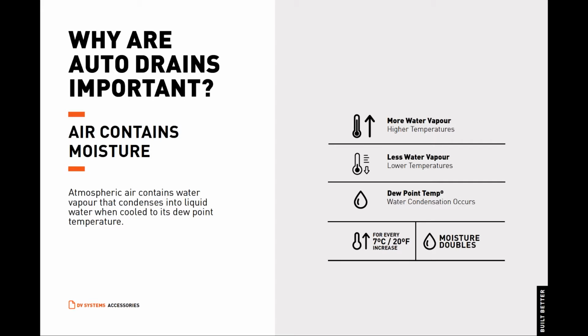An accumulation of moisture condensation in the air receiver tank will eventually limit air compressor performance, potentially result in the presence of moisture in the air lines, and cause an air receiver tank to deteriorate prematurely. Air dryers and inline filtration will also not perform if they become overloaded with liquid contamination. Also, water can back up into the air compressor and damage the machinery. Ultimately, an inconsistent supply of dry compressed air will cause production problems. For example, moisture can wash away the lubrication from air tools, causing erratic performance, downtime, and maintenance.